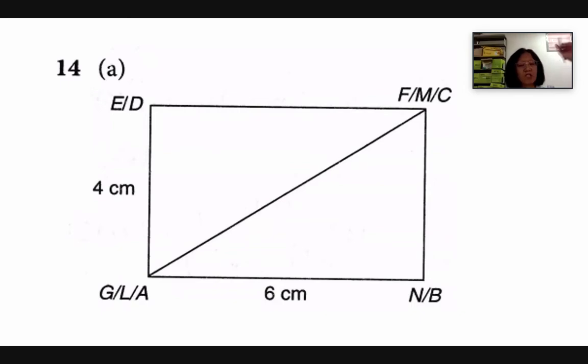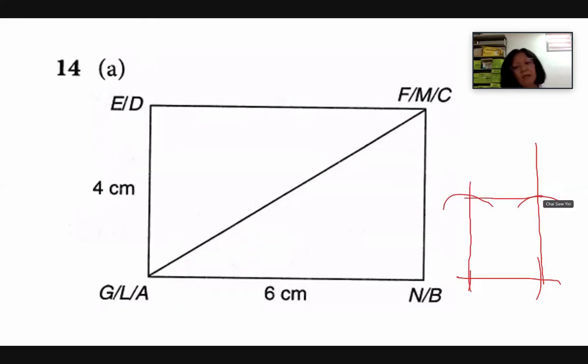Use your pencil, sharpen your pencil the night before so that when you draw the rectangle, it will be one straight, fine, dark line, not a thick line, because we want accuracy. Measure the length 4 centimeter, then draw an arc, something like that. It's better to have an arc like this. Here also measure 90 degrees. Draw it. Then join it. You will get a perfect rectangle.